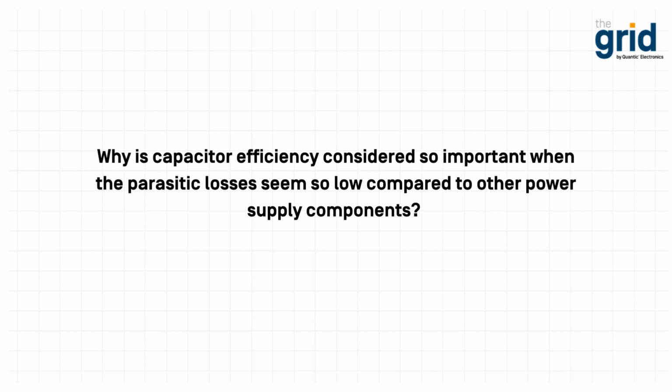Also for bidirectional and resonant applications, that steady impedance over frequency and temperature allows for the converters to be used efficiently across a wider range. The alternate to that is to stack multiple capacitors in parallel or multiple converters in parallel, and only operate a few at a time to mitigate that. As battery and renewable electric mobile applications continue to increase, I can see this becoming a bigger and bigger consideration because when things are being powered mobily, every bit of efficiency counts.